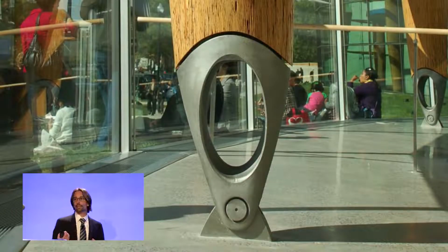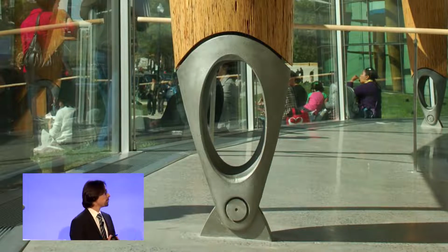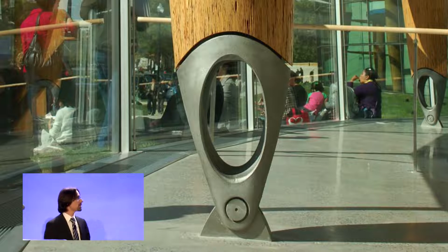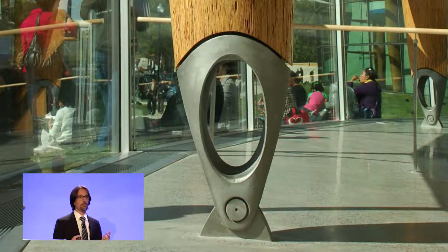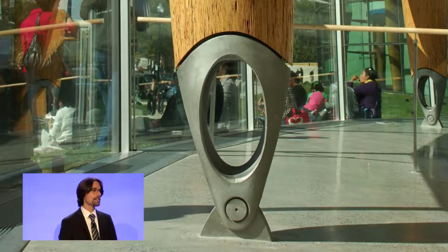And as I said, with castings, we could put the material where it wants to be for the flow of forces through the connection, or we could kind of ignore it and just make really interesting looking connections. These particular connections are at the bottom of timber columns, obviously exposed at very close view, so people can actually go up and touch and feel these castings in the structure.